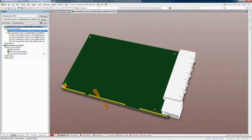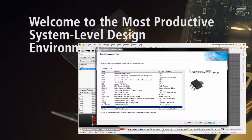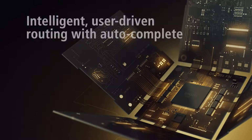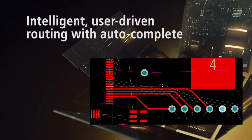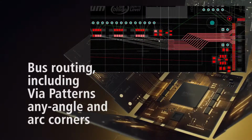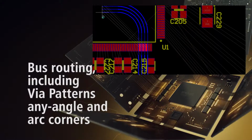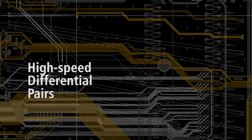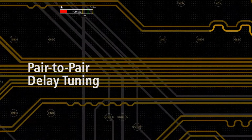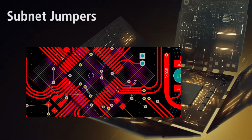Once you're routing the board, Altium Designer's world-class and award-winning PCB editor has everything you need to get the job done accurately and quickly. Altium's goal is to make the best PCB design software available with advanced interactive routing with autocomplete, any angle routing, bus routing including via styles and arced corners, high-speed differential pairs routing, pair-to-pair length and phase tuning, net class length tuning, automated pin and gate swapping with subnet jumpers for auto completion,